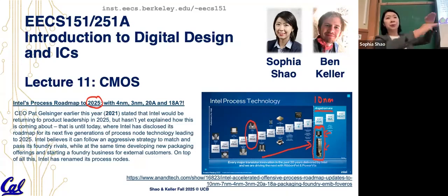So when we think about a wafer, when we do transistor manufacturing, we start from transistors and all the metal layers. But it's always a mix of power delivery metals and signal metals. So what Intel actually did first is move some of the power delivery metal layers from the top of the wafer to the backside of the wafer.